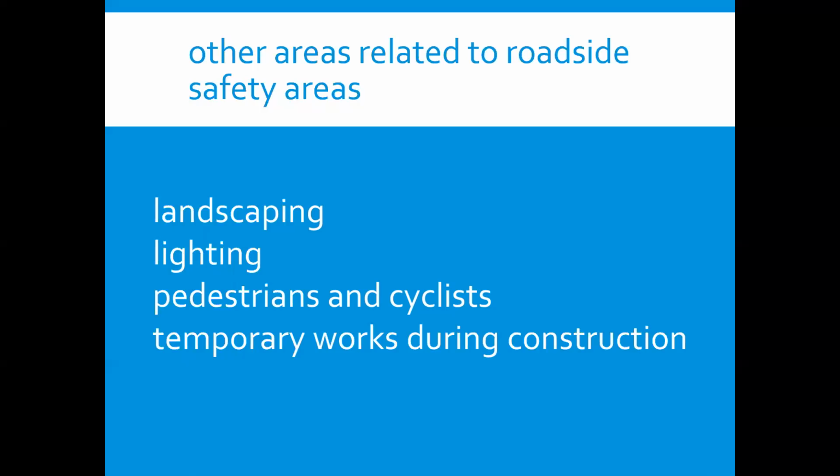In relation to pedestrians and cyclists, in design of a safe road environment consideration must also be given to non-vehicular road users. The needs of pedestrians, including those with disabilities, and cyclists are discussed in various guidelines. The safety issues to be addressed for on-road cyclists are very similar to those relating to motor vehicles. It is important for the road surface to be smooth, to minimize conflicts, and to provide appropriate delineation.